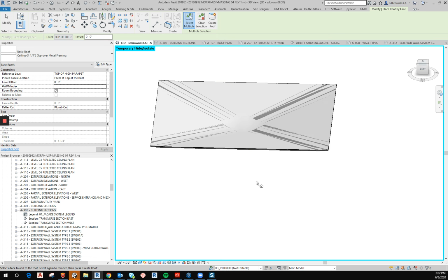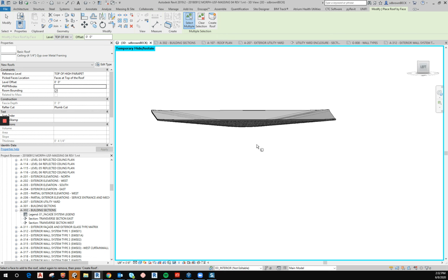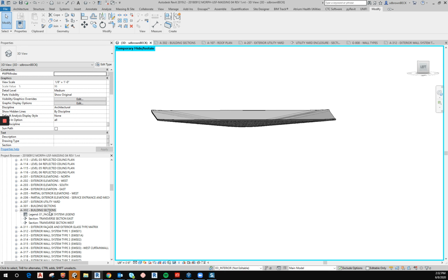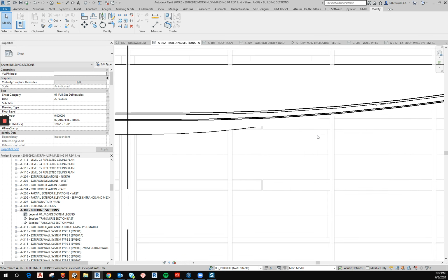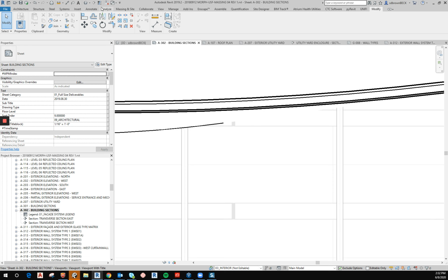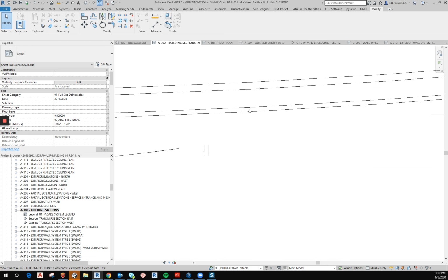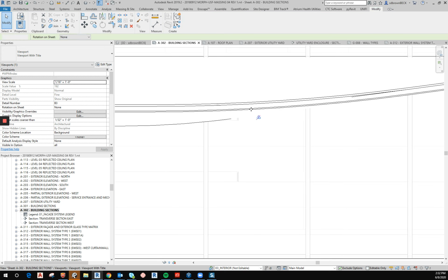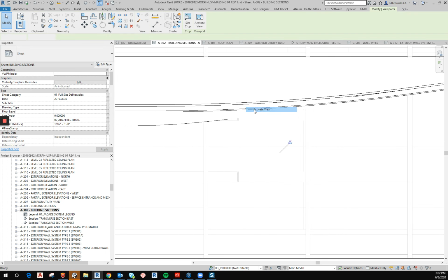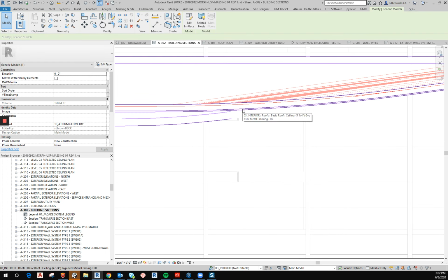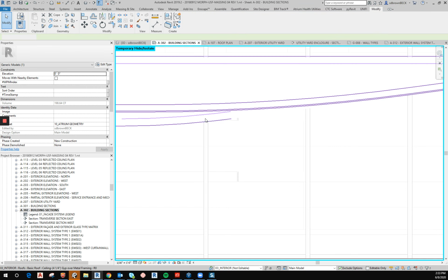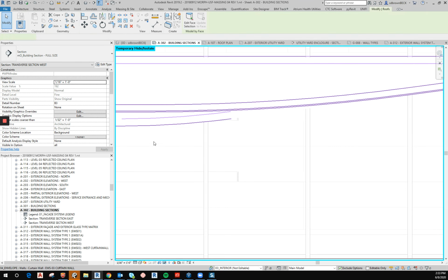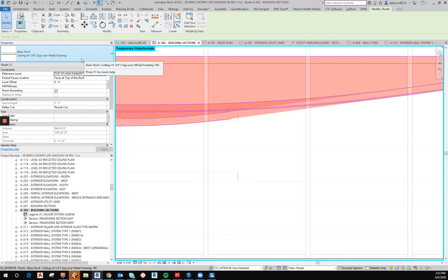Create roof. And then we can go back to our building section. And you'll see that this now has the different layers in there. Going to go ahead and hide that real quick. That's the form element, but we are left with an actual roof type that's real.